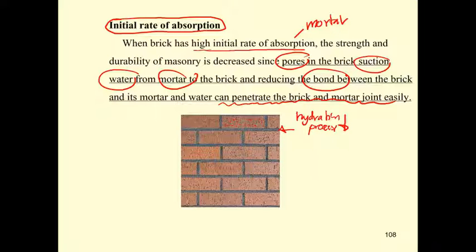And if the water can penetrate the joint easily, under the condition of freezing, that's going to expand the crack or expand the void between the brick and the mortar. And also if the water penetrates into it, the water may go deeper and deeper and may make the masonry less durable.